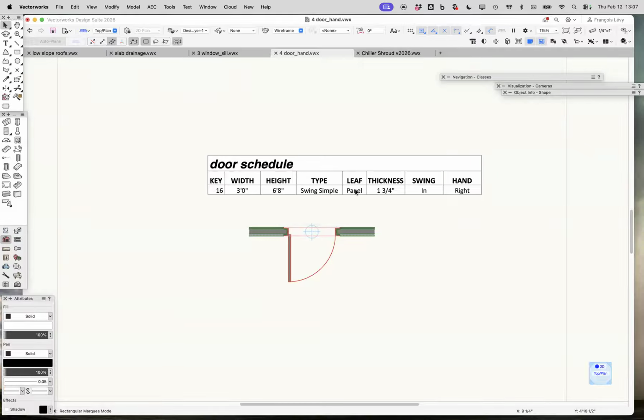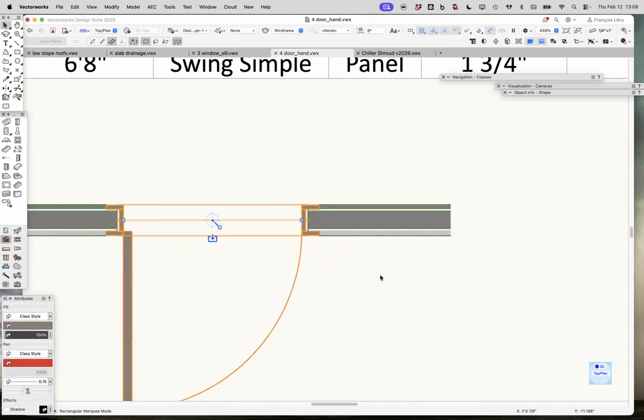So, Francois, may I jump in? Yeah, this works well if it's an exterior door. And this was my question, so I'm not ashamed to admit my confusion here. If the door is opening inward, the hand works correctly. But if it's an exterior door opening outward, it doesn't. It works for an inward swinging door, but looking from the outside, which is typical in this case, the hinge side would be the opposite. I don't know which is the interior and exterior on yours. Yeah, this is an outswinging door.